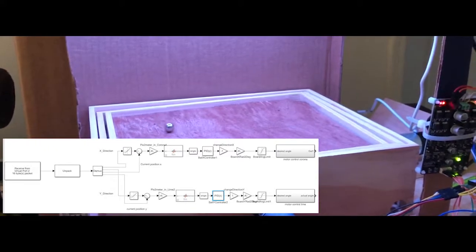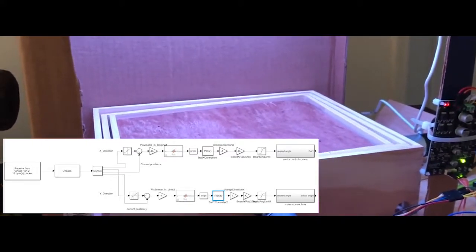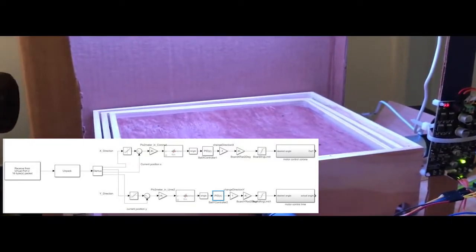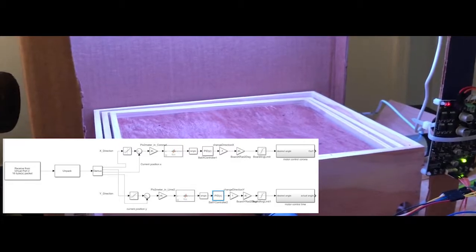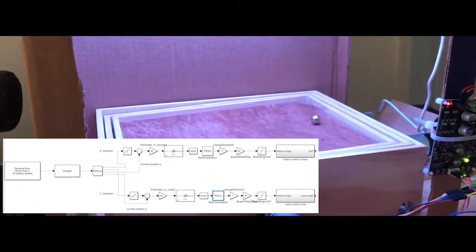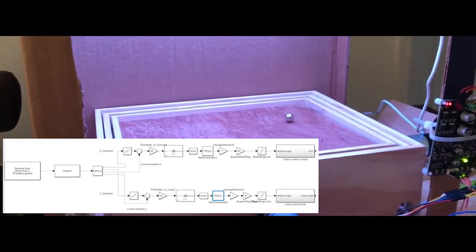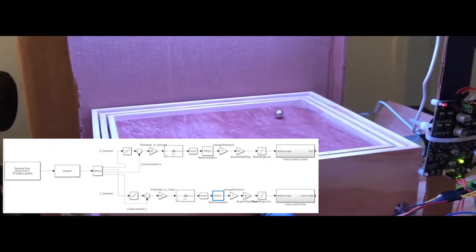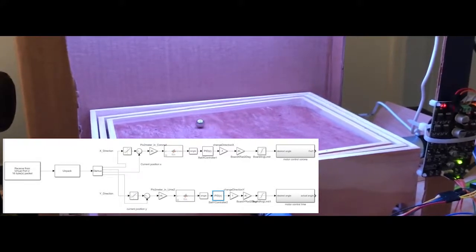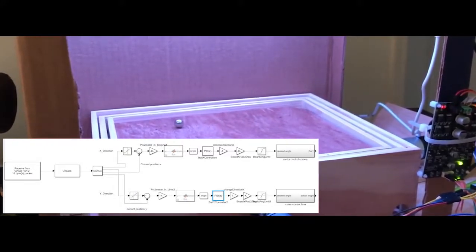First, we have the block that receives the data from the visual port, and it's 16-byte data. It's receiving four pieces of information: the X and Y coordinates for the desired position and the X and Y coordinates for the actual position registered by the visual feedback.